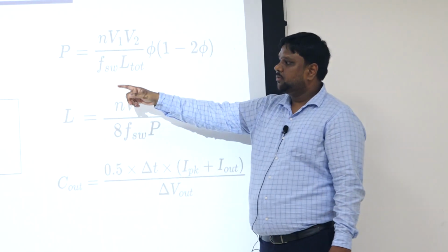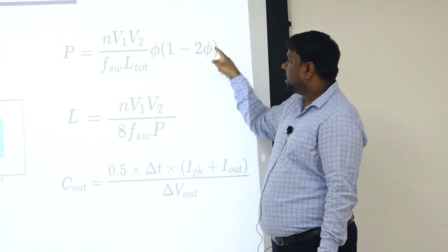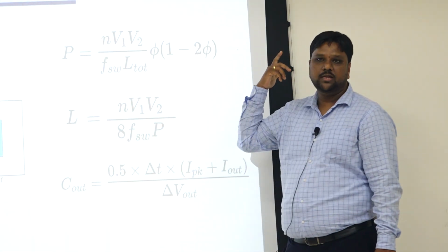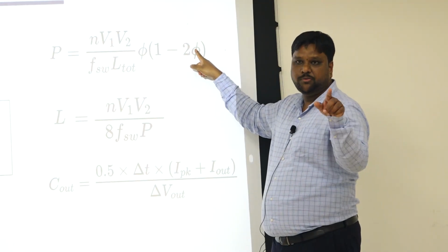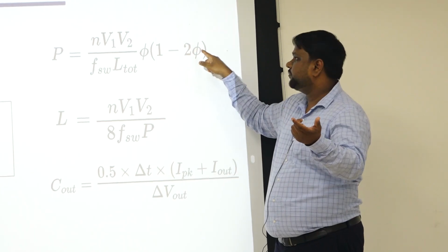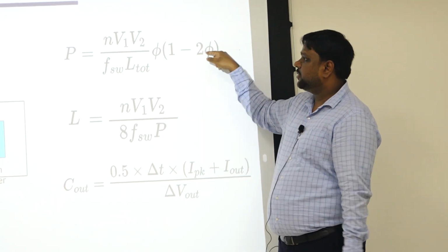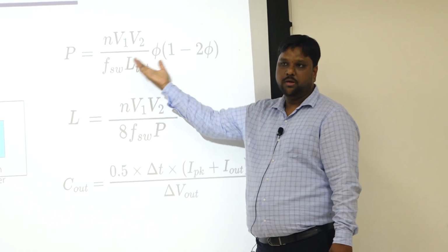And for this converter, the power transfer equation is basically this, and this phase is the phase you have to control, so that power is shifted from the primary bridge to the secondary bridge. How do you control this? You can use any kind of controller. The final output will be phi, like the u of t I was writing. From u of t you have to convert to phi, because it is a phase. That phase has to come here, and by controlling this phi you control the power transfer.